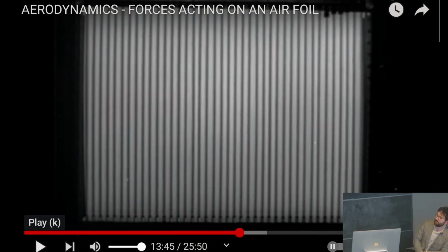So that is a bank of manometers. I don't know how many are there, but that's a lot of different manometers. All those lines are tubes filled with, I'm not sure what they used here, maybe water or something. So you can connect each of those manometers to a different spot on your test geometry, and you can measure pressure distributions that way.